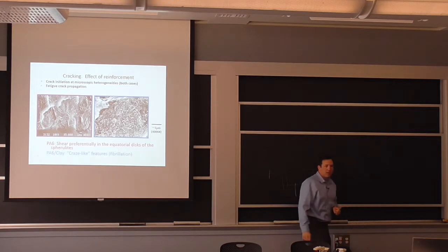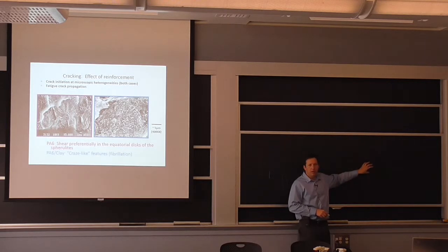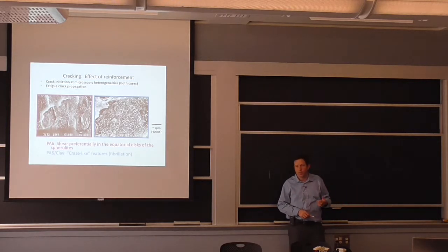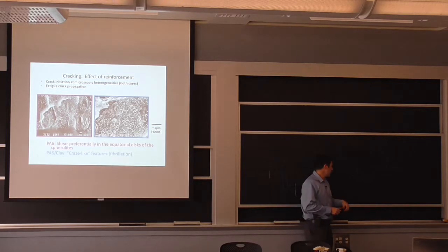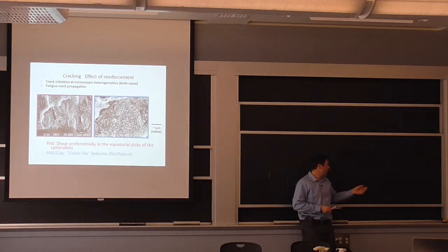It could grow bigger than that in that direction. So it's broken down from the natural clay product. The consequence of that is, if you have these particles and you manage to disperse them in the polymer, there's a lot of processes involved in making this happen. You have to functionalize the surface, essentially get some polymers to bond to it, so you don't have all the particles just agglomerating together. They stay separate, and they form a distribution in the melted polymer.